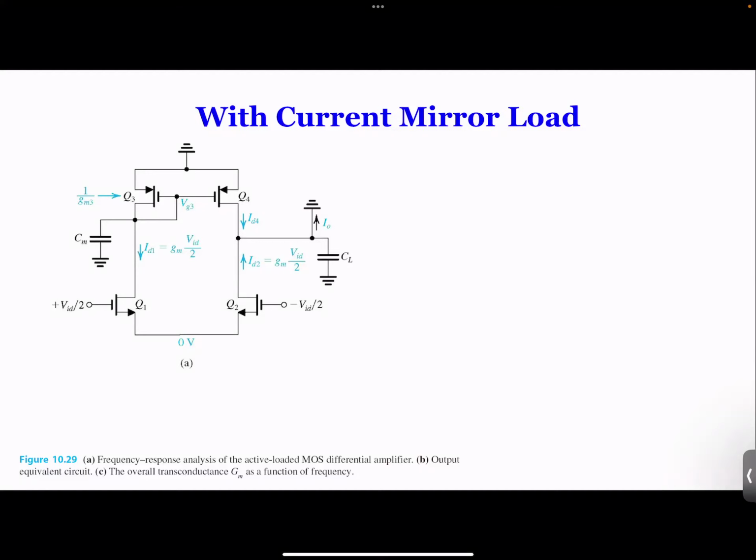We always want to use a current source as a load, which increases the resistance by itself. The intrinsic resistance RO is big, which is good. And also, it's easier to make a transistor than to make a resistance in an IC design. So if you look at integrated circuit design, you always have some current source as a load instead of a resistance.